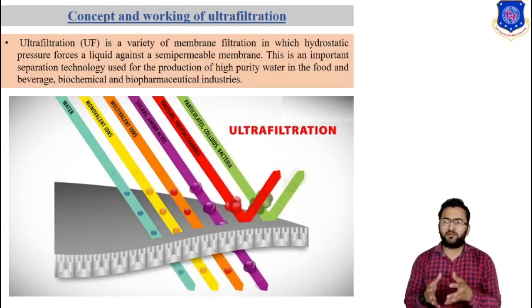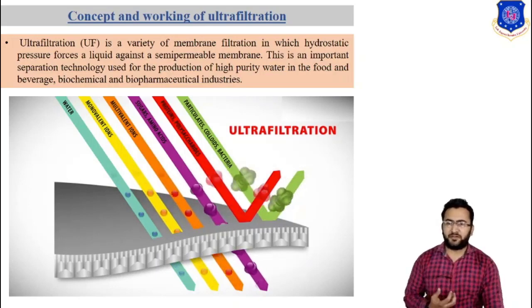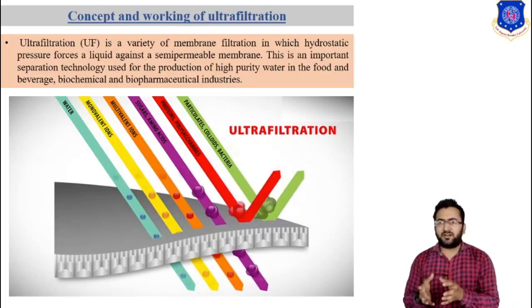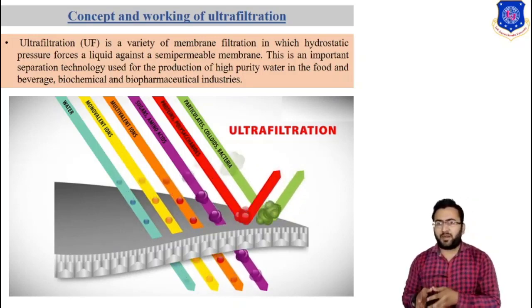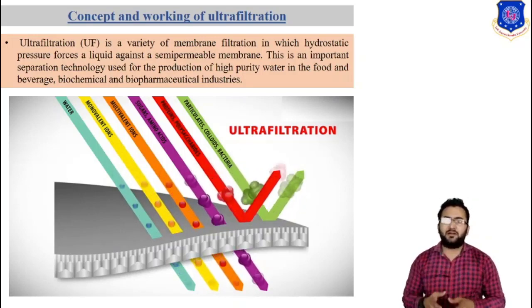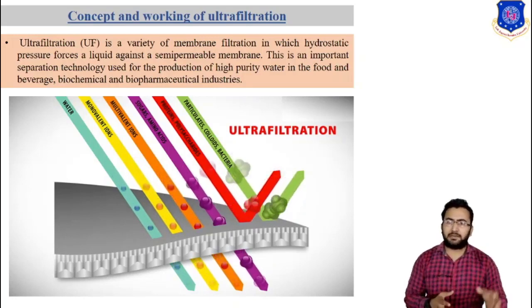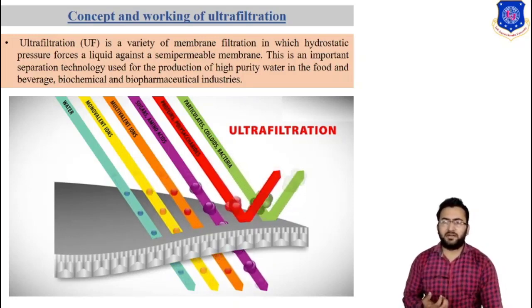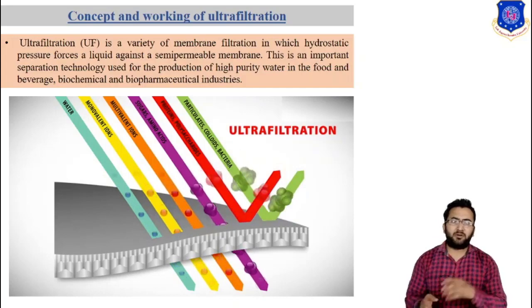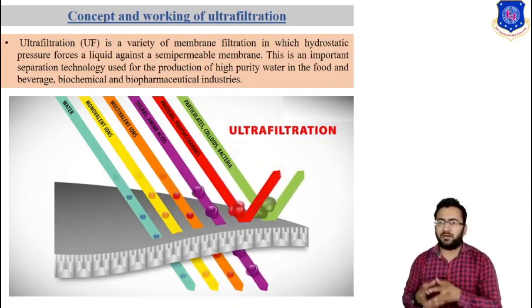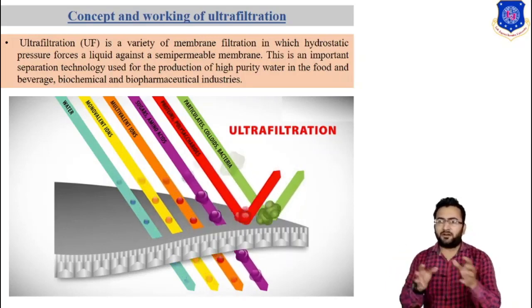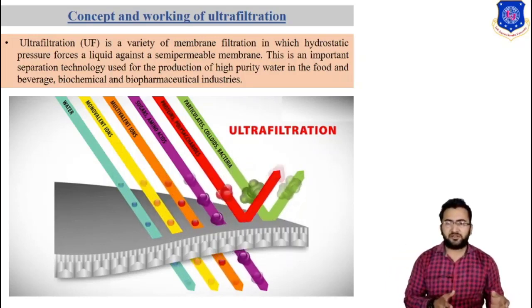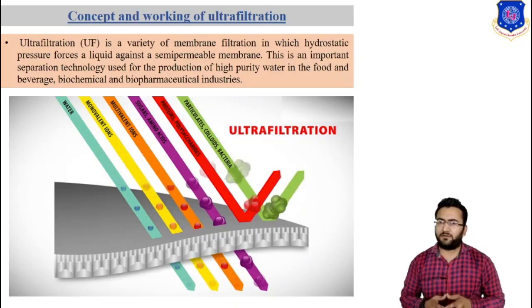Some pore size distributions may be polydisperse. Polarization effect of protein at the membrane may alter the measured value, and significant accumulation will result in autofiltration. This result is a measure of the boundary layer rather than the membrane itself. So these are all limitations of the molecular weight cutoff characterization technique used for ultrafiltration.